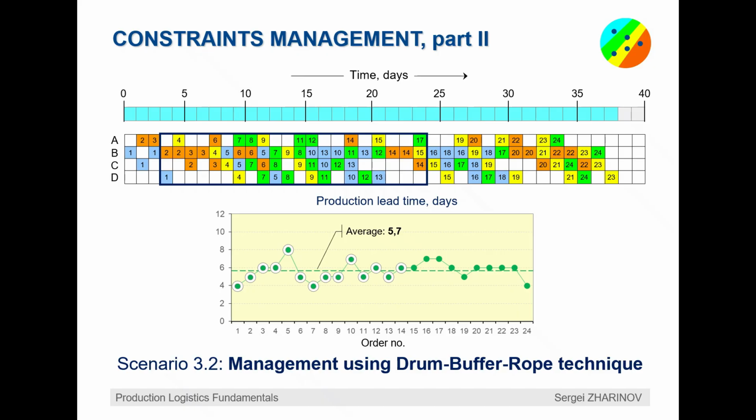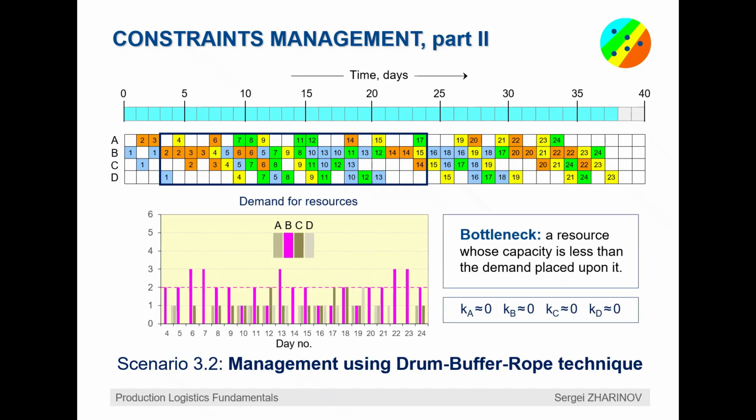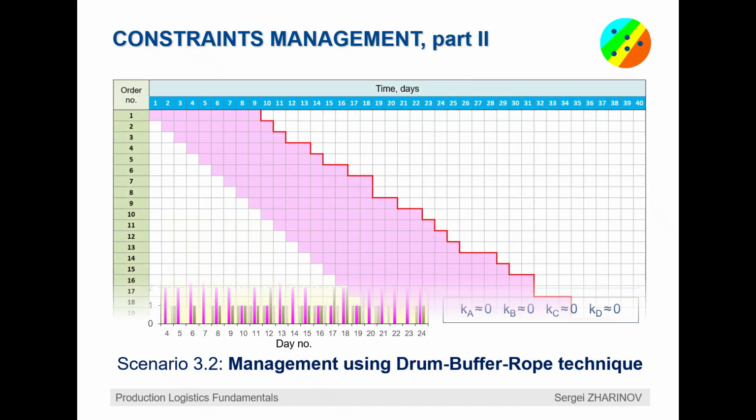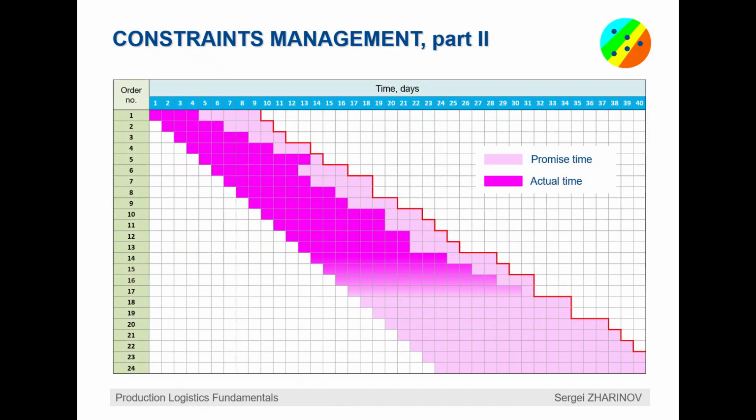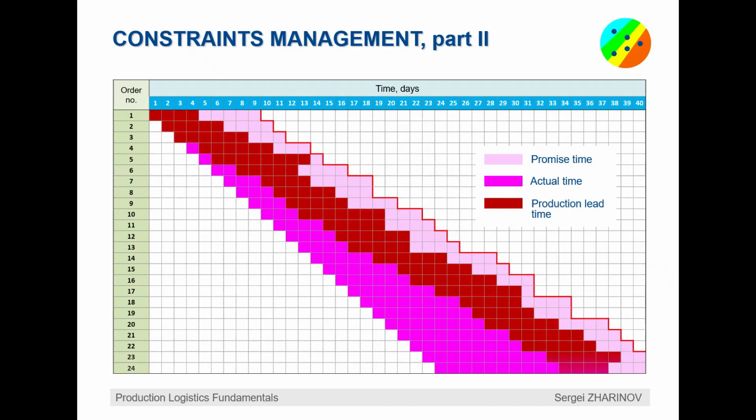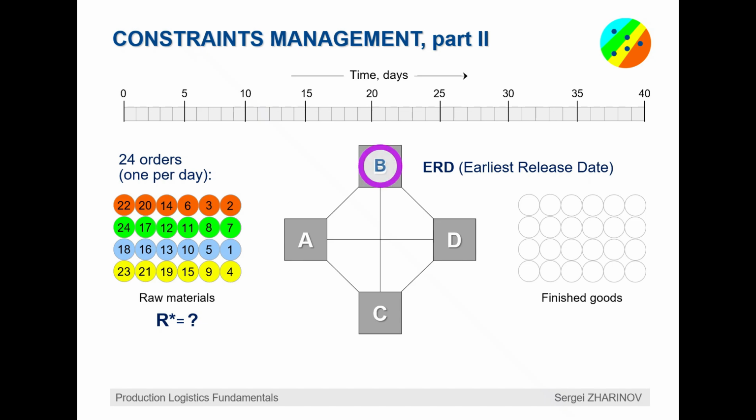There are no bottlenecks either, and given the same 9-day maximum production time, the promised due dates are perfectly adhered to. Comparing the original and the 2 additional scenarios discussed above clearly demonstrates the system's resilience to changes in control parameters. The key point is that the capacity constraint B is the only resource worth worrying about loading. Moreover, from the whole system management perspective, the cycle time for other resources does not really matter, and for the resource B it may only be approximately known.